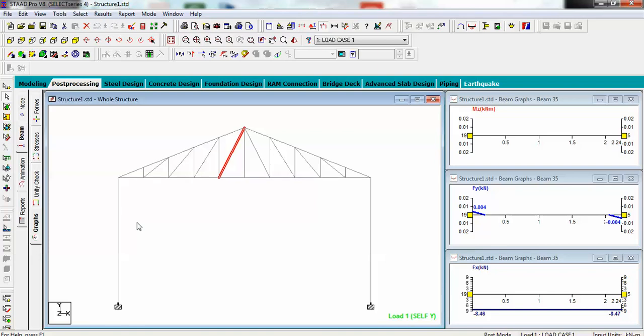So now this portion was the steel design, but now we have to enter interactive steel design. That is a very important one. Let me tell you one case. As I told you, Staad Pro automatically gave me some suggestions for section profile for different members. So consider this is a beam, and at this particular point, if the load is greater, then Staad Pro will suggest using a bigger section at this point of the member. But if my section profile and size are different here, then it is not feasible, it is not practically possible.